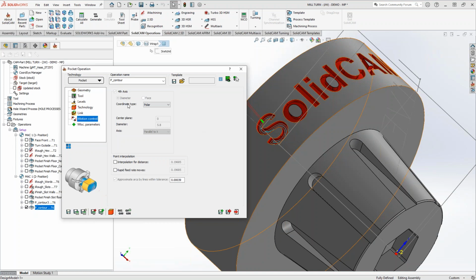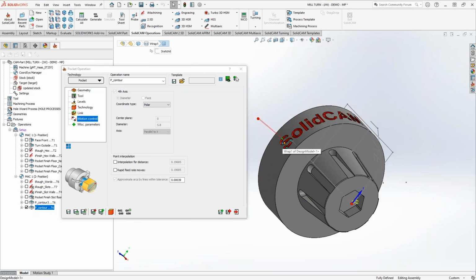And you will see this pop up when you do anything on the face like we did in those videos, or here, you can see it actually grayed out because it read it from the diameter. So this is just on the diameter side of things. Now the rest of this window here is grayed out only because we started with wrapped geometry. So that geometry gave us the center plane, gave us the diameter, and figured out that it was parallel to the x-axis.